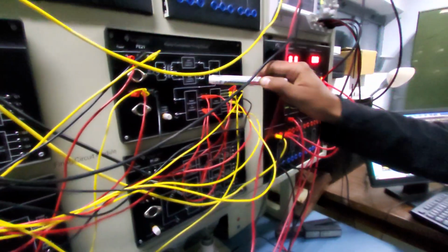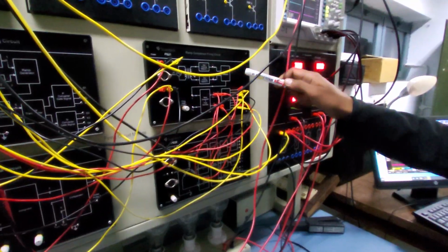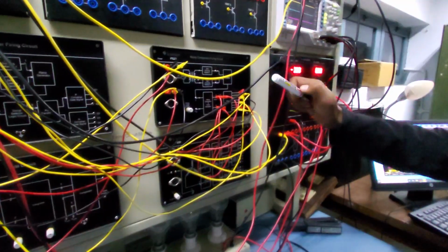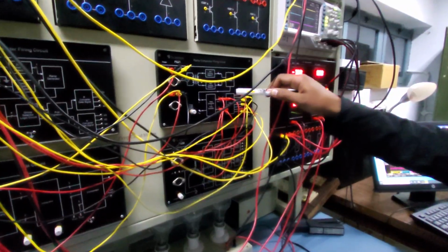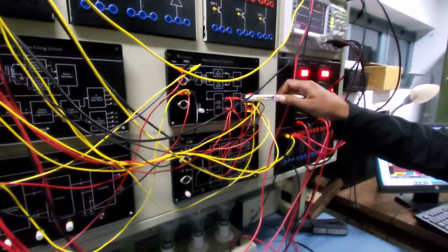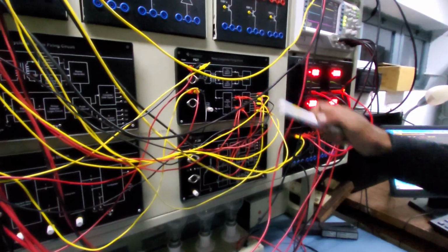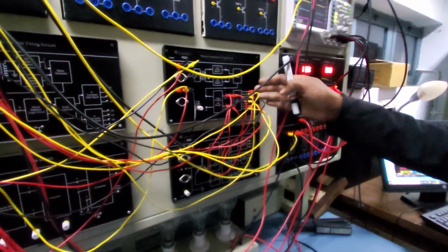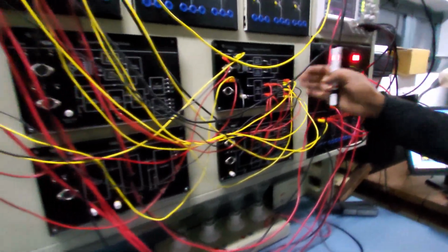Again, the comparator signal is a low voltage signal, but we are required to amplify or convert this to high voltage due to the requirement of the power switches. Another important thing is isolation between the low voltage side and the high voltage side. So we need a pulse transformer to provide high voltage isolation between the high and low voltage sides. From the output of the pulse transformer we get various pulses, G1, G2, G3, G4, which are the 4 gate pulses for the 4 switches.